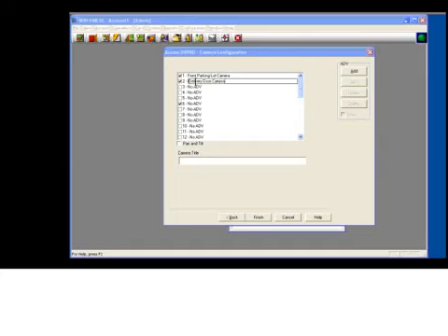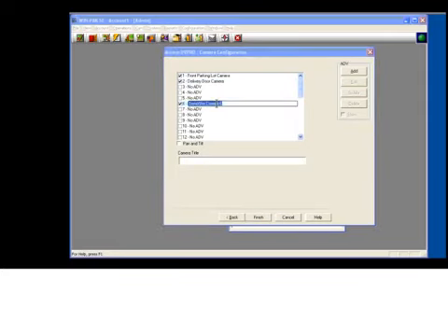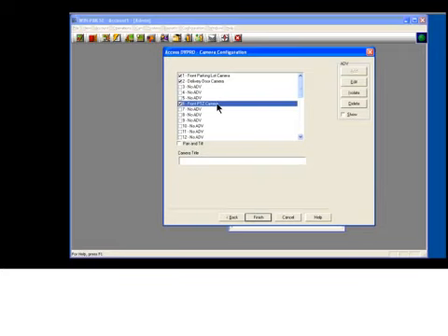I do recommend being as descriptive as possible. If there were multiple sites, you might want to call this the Beck delivery door or main building delivery door, etc., so that you can recognize what each device is. And then we'll take camera number 6, and we'll double-click on it, and we'll call camera number 6 front PTZ camera. Now, camera number 6 is a little bit different. Camera number 6 actually has a PTZ control assigned to it. So down here where it says pan and tilt, we're going to hit the checkbox. Camera titles will be descriptions that you might want to push back and forth if you were using a switcher. Okay, so we've got the front lot camera, delivery door camera, and we got the PTZ camera.